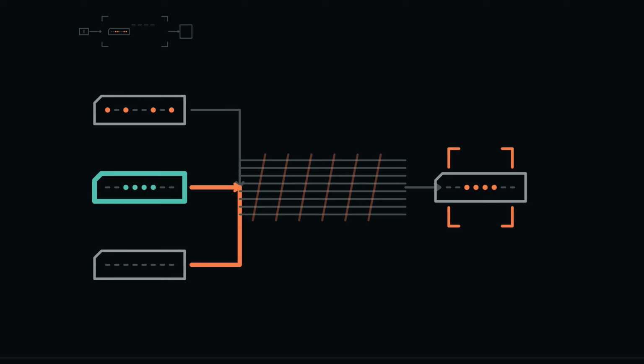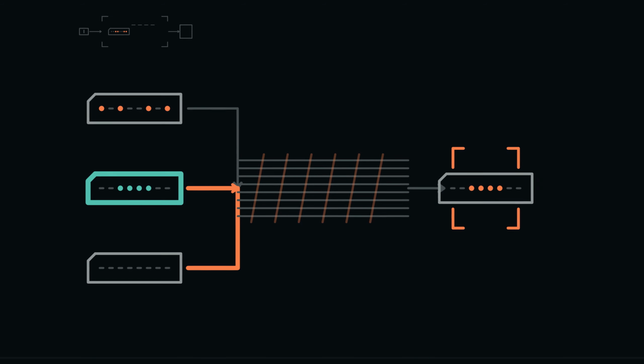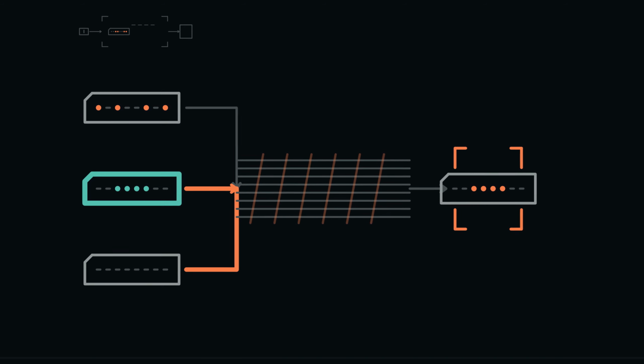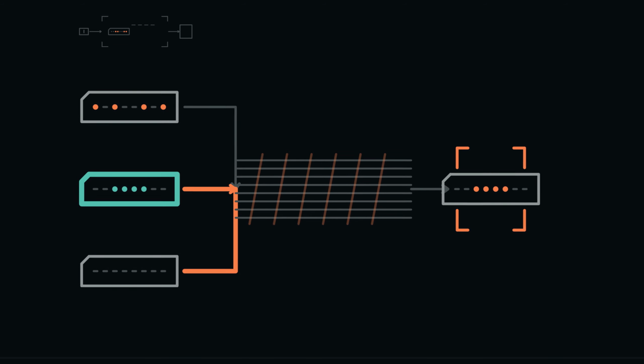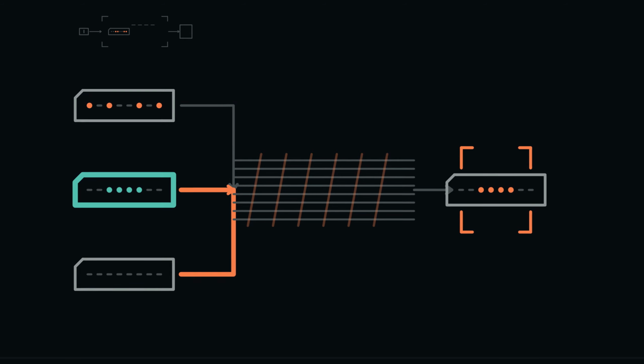This is contention. Incompatible drivers attempt to control the same shared connection. If two sources happen to hold equal patterns, enabling both is still a design error because correctness would depend on an unnecessary and unsafe coincidence.